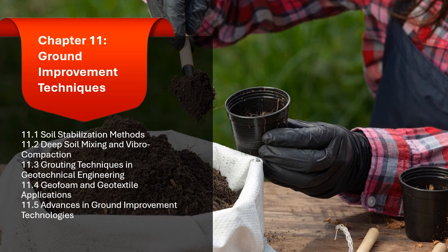1.3.5 Limitations of grouting. Soil characteristics. Grouting may not be effective in soils with very large voids, highly fractured rock, or highly permeable materials, where grout may not adequately fill all gaps.